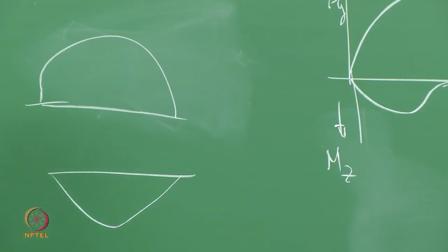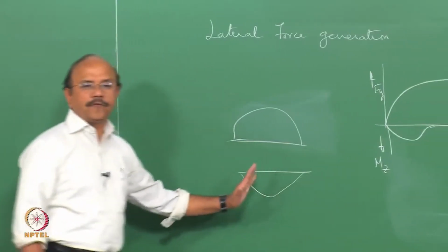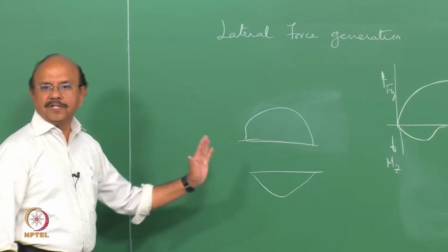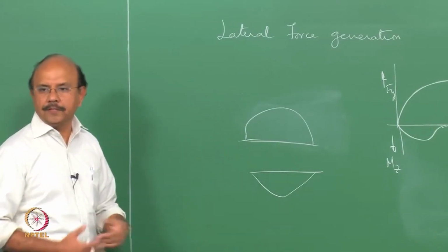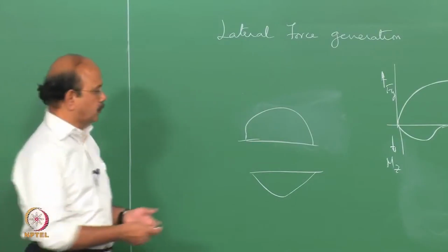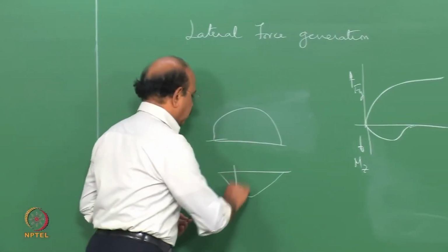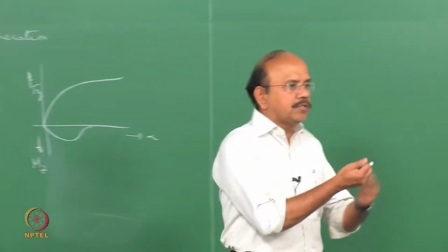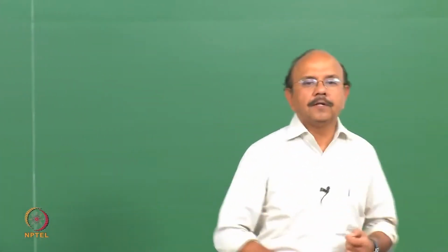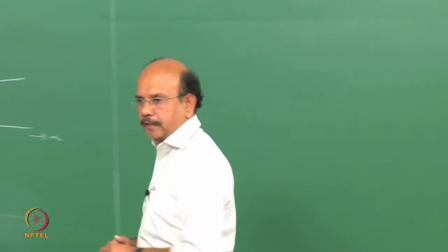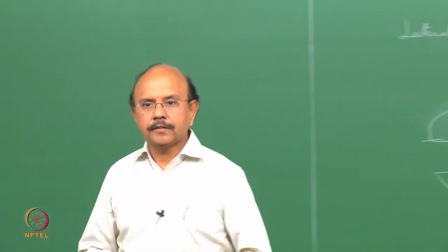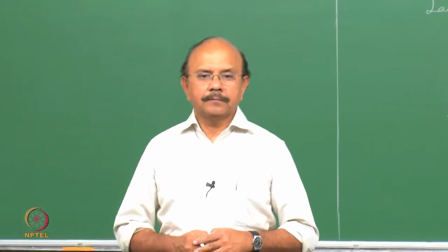Assuming that there's no slip, because it is now shifted to the left, there's an unsymmetric distribution, so obviously the resultant force, because of all those shears or pulls of those bristles, will not be symmetric, but unsymmetric, right?